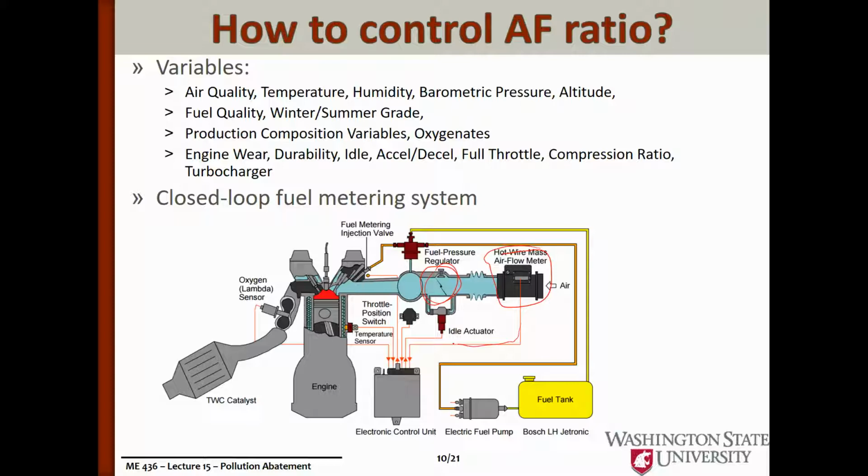So this introduces significant error, but that goes to the brains of our car, our ECU. And then we need to measure what the oxygen was in the exhaust. If we know we want to burn it stoichiometric, there should be essentially 0 oxygen left in the exhaust.